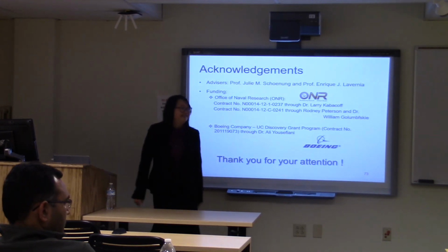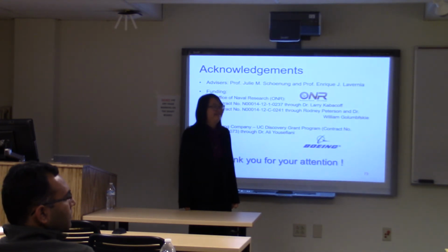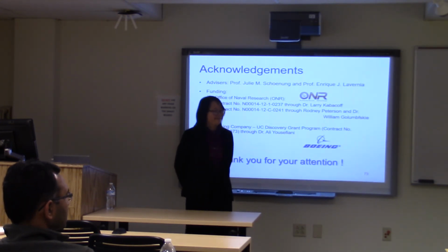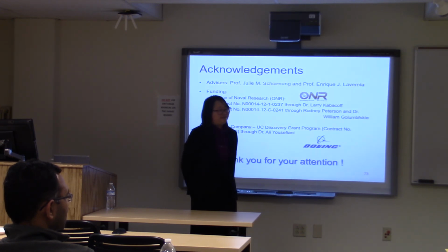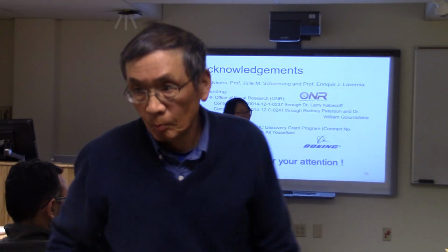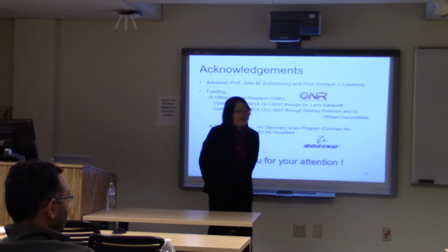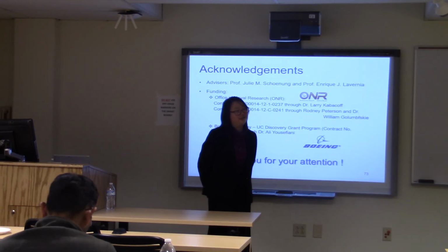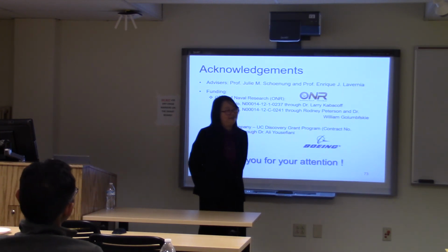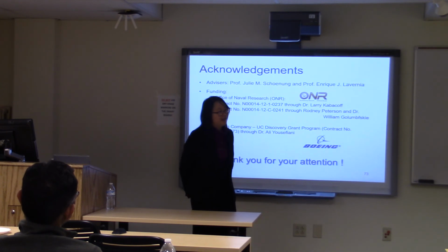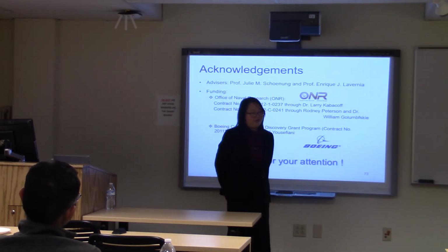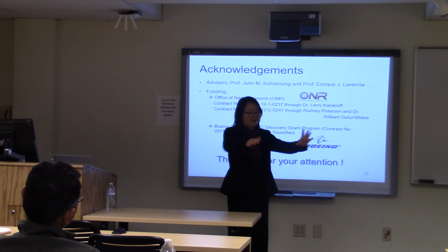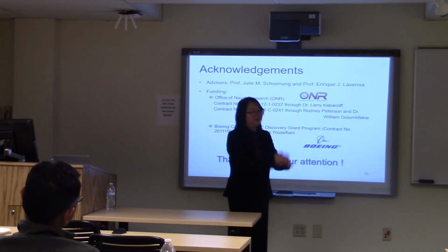So if I probe into Jason's question, you said that when you do the ultra-fine material, you lose ductility. Yes. But you don't necessarily increase the likelihood of fatigue, right? I mean, is it possible that crack propagation would be inhibited? Grain boundaries should, theoretically, be a very good barrier to stop crack propagation. But if the crack propagates along your grain boundary, then that's another issue there.